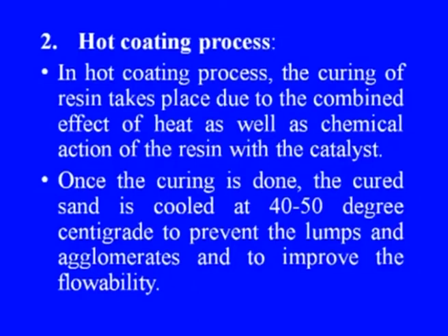The second process is the hot coating process. In the hot coating process, the curing of resin takes place due to the combined effect of heat as well as chemical action of the resin with the catalyst. Once the curing is done, the cured sand is cooled to 40 to 50 degrees Celsius to prevent lumps and agglomerates and to improve the flowability.